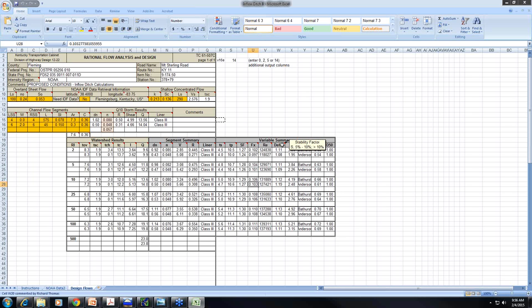This is a stability factor. It brings into play the side slope. Stability of the riprap is dealt with in a particle fashion, using vector drag and forces and shear forces from the water and slope, not only the slope of the ditch but the side slope, and it's kind of hairy getting into, but anyway, it aids in calculating the safety factor due to the side slope impacts, and then of course the area and the method that was used to arrive at the relative roughness N value.